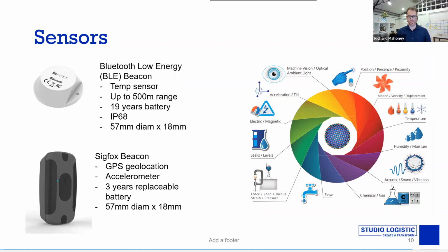Bluetooth low energy is the same technology but much lower bandwidth, something in the order of about 200 kbps, which is something in the region of what a dial-up modem would have been once, but it's probably not enough to support voice, but easily enough to send a temperature reading once a second or something. So setting up sensor networks around DCs is something I think you're going to start to see more of.